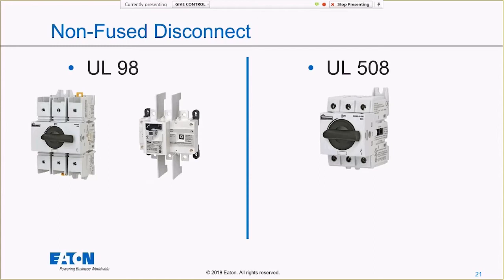And with non-fuse disconnects with trailing fuses, a lot of times I can get that 100 or 200 kA rating without a problem. When I use a non-fused disconnect, it's really important that there are two different UL ratings you can have. UL98, that's the good one, the top of the line level. UL98 disconnects can be used in feeder circuits. They have the spacing requirements needed to be used as the main in that feeder circuit, and there are limitations in there.